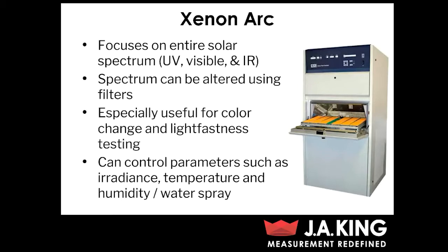And the next type of testing I want to talk about is Xenon Arc testing. Unlike fluorescent UV, this is going to focus on the entire solar spectrum. So not just UV, but also visible light and also infrared radiation. And the spectrum can actually be altered a little bit by using different types of filters. So some of the most common filters are daylight and window glass filters.